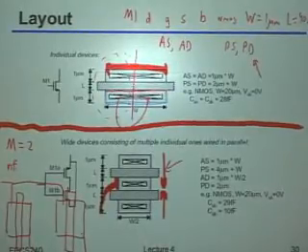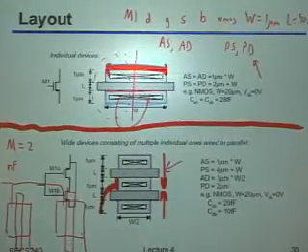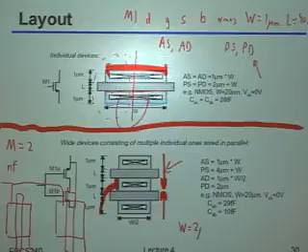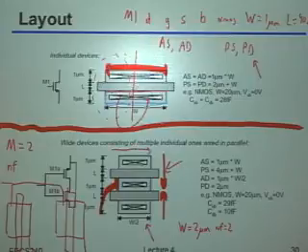Whereas this so-called NF typically means that you're taking some transistor, and I'll explain how that's typically used. If I had a transistor that, for example, had a W of 2 microns, but an NF of 2, what that typically means is you'd end up with a layout that looks like this, where each of those widths is actually 1 micron. Okay?